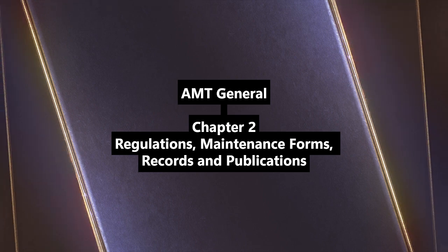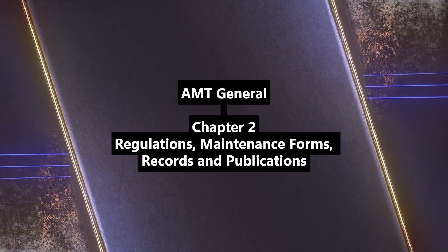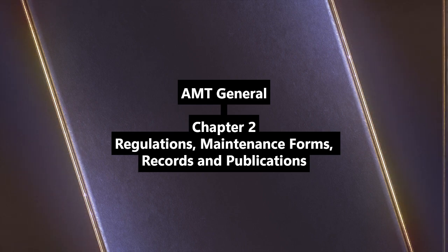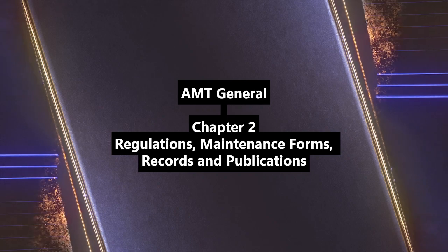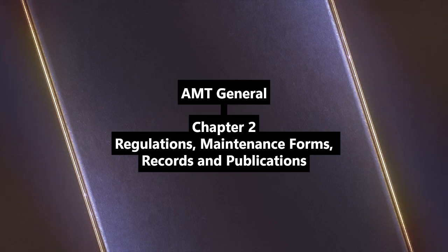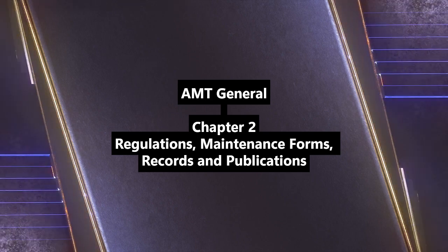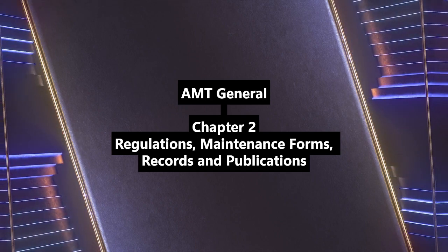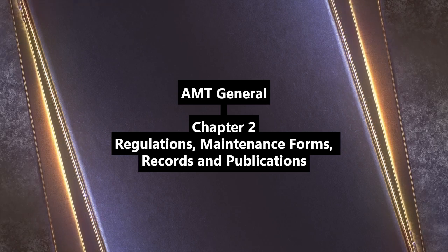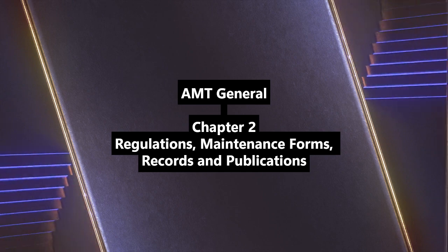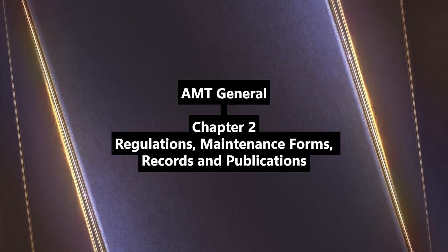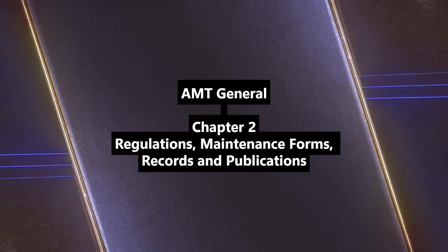14 CFR Part 21, certification procedures for products and articles. This is the rulebook for getting type certificates, TCs, supplemental type certificates, STCs, production certificates, airworthiness certificates. Import-export approvals. Yeah. The whole initial certification process. Exactly. Its main focus is that original airworthiness, but it definitely impacts ongoing maintenance, too. While Section 21.50 is key, it covers instructions for continued airworthiness, the ICAs. Ah, the maintenance manuals and instructions. Right. When a new aircraft is built, it comes with these ICAs specifying all the required maintenance.